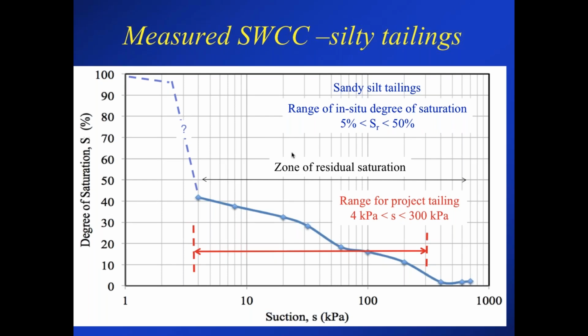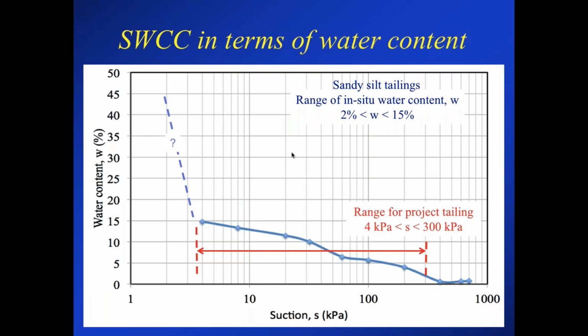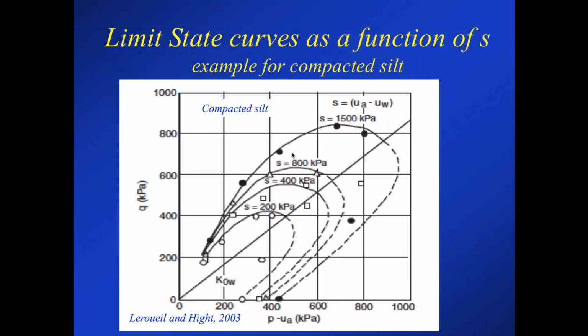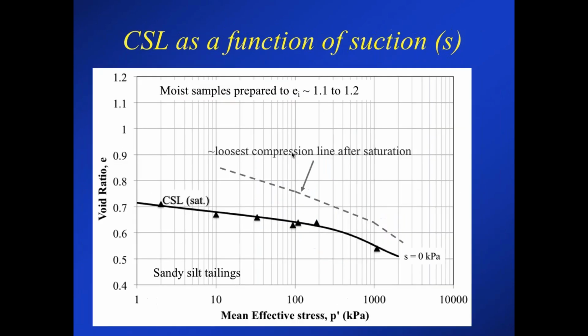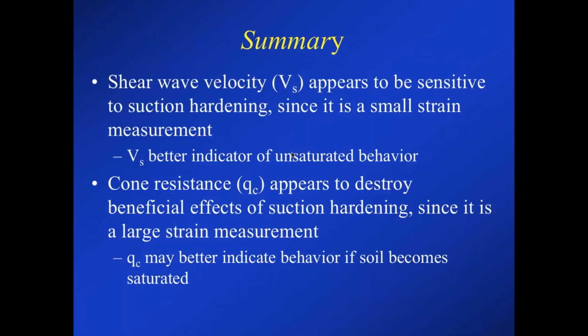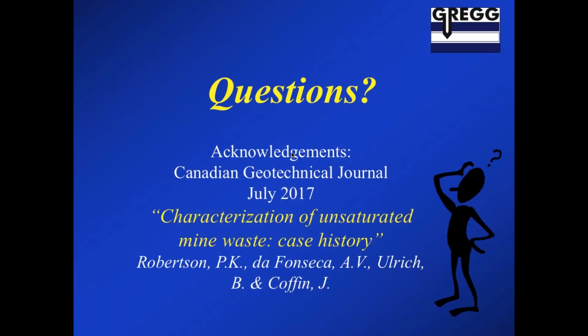Next question. What do you think about the speed of penetration, its effect on saturation? Yeah, okay. So we sort of said that at the standard rate of penetration, one could argue that we had partial drainage during that standard rate of penetration, supported by these relatively rapid dissipation tests. Now, a school of thought would be, well, if you ran the test faster, could you have pushed it into the undrained region? And if you ran it slower, could you have pushed it into the drained region? And the answer is yes, that's probably true.